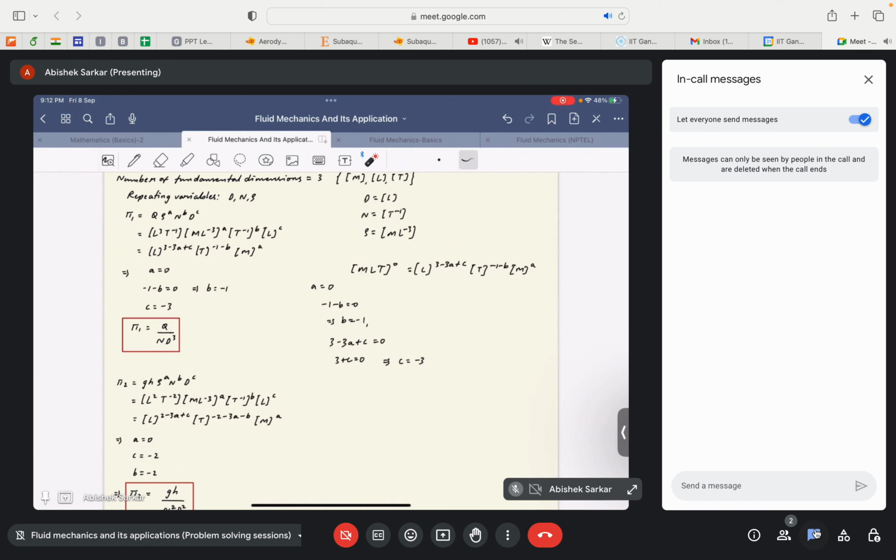By having an idea of these non-dimensional pi numbers, we can play with them if we are conducting an experiment, and see which parameter affects the flow most, and which variation affects the flow least, and so know which parameter actually drives the flow. I hope it was clear.